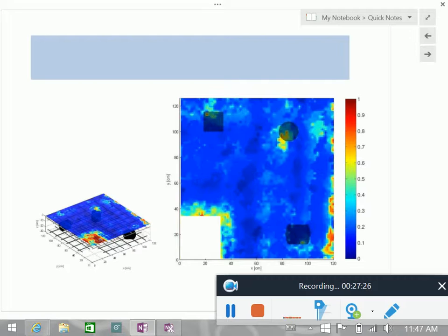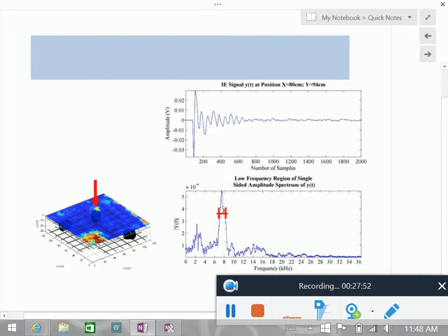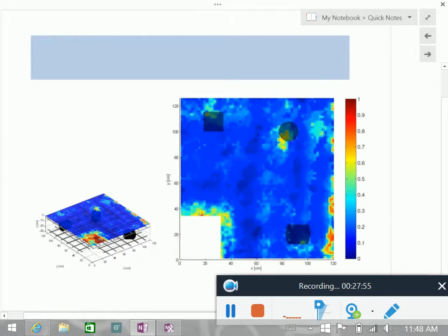It's not because it created a boundary, it's because it attenuates. So when you have this kind of honeycombs, it attenuates the wave a lot more than when you don't have them, because you have these pores inside. And because of that, the width becomes larger, and at those locations you are going to see that. Again, I'm not making the assertion that this is a very good method for this application. This is just to show you that this can work. But for this application, this is a little bit too rough from my perspective.